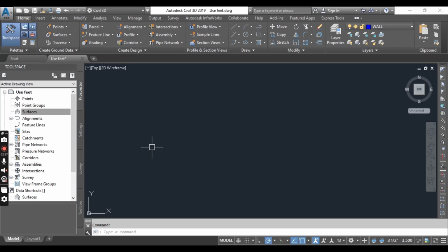The best course of action when receiving an outside drawing is to insert it into a blank file that you started using your Civil 3D template. When you insert a drawing, Civil 3D does several things to help you. The first one, the insert command detects the units of the incoming drawing and scales it to match your drawing. If both drawings have a coordinate system defined, Civil 3D places the incoming drawing by geographic data. All of your styles and settings remain intact. In this exercise 1.4, we will practice this situation.